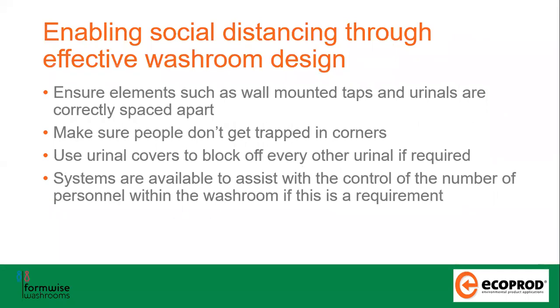And then think about the elements required for delivering effective washroom design. Wall-mounted taps and urinals correctly spaced apart. Make sure people don't get trapped in corners. Tim's already touched on urinal dividers. In the current period, you might have to cover off every other urinal if required. And there are actually systems available now to control the number of personnel within the washroom if this is considered a serious requirement.